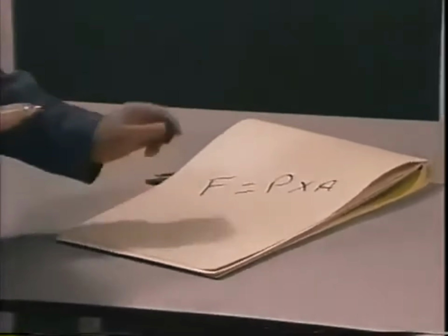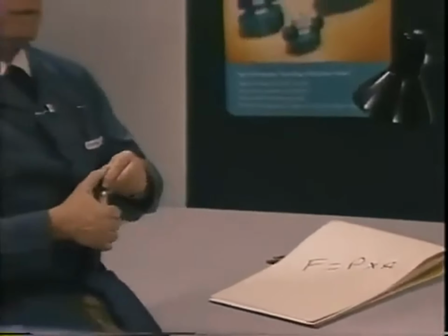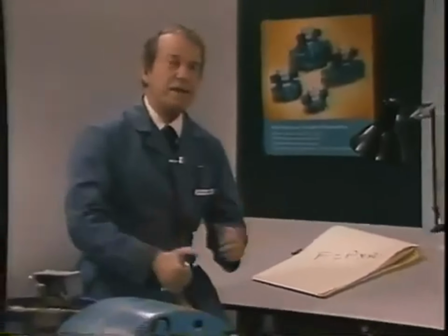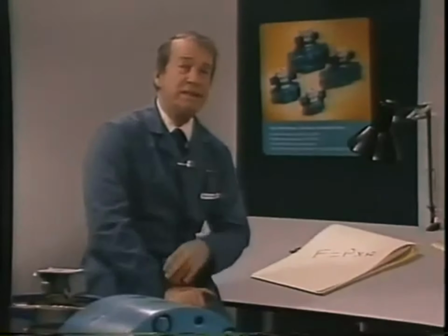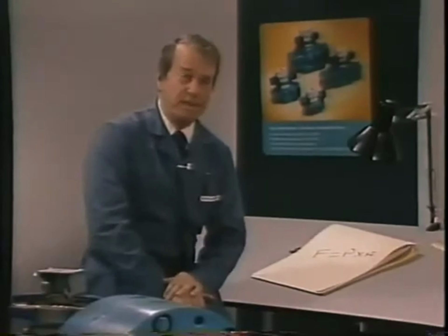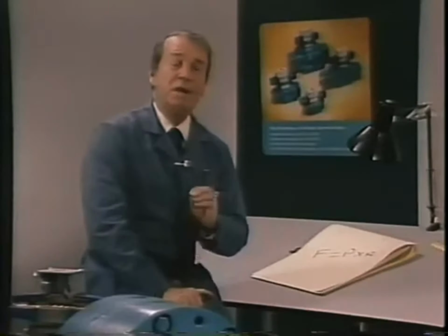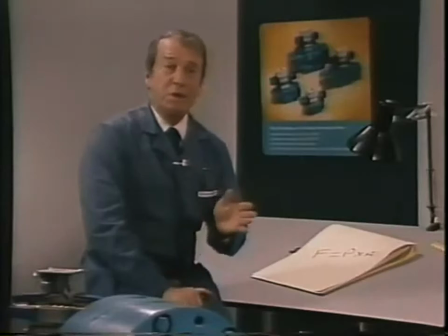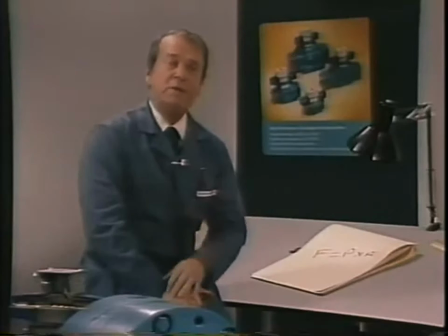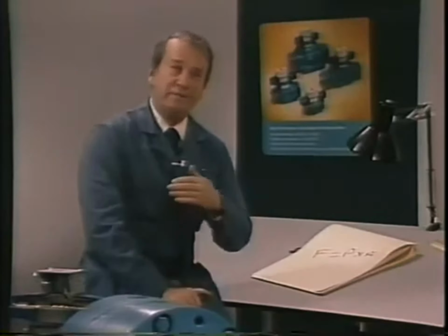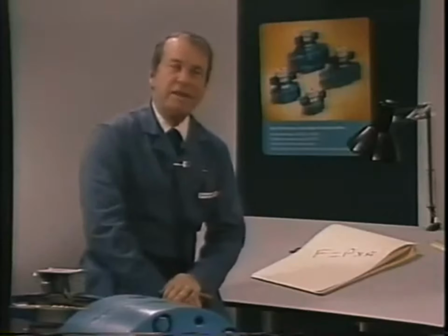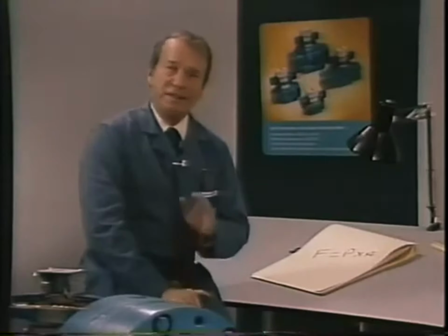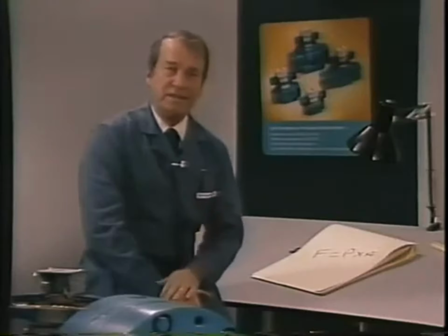Since the rod reduces the effective area of the piston, the force available when retracting the piston will be less than it is on the forward stroke. The rod, however, will partially fill the cylinder, so less fluid and proportionately less time will be required for retracting than for extending. Here again, what's gained in force is lost in speed or distance.